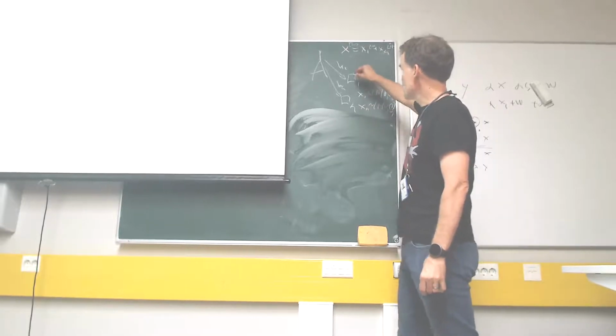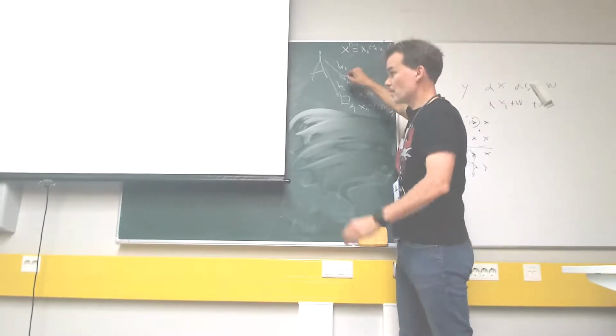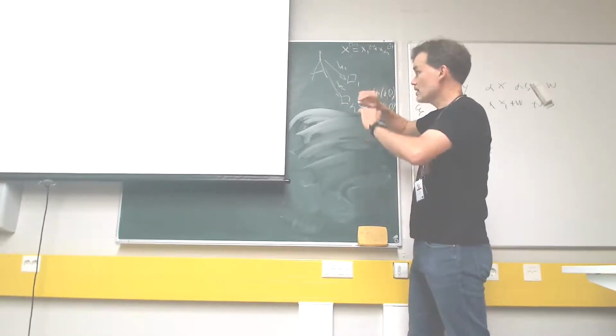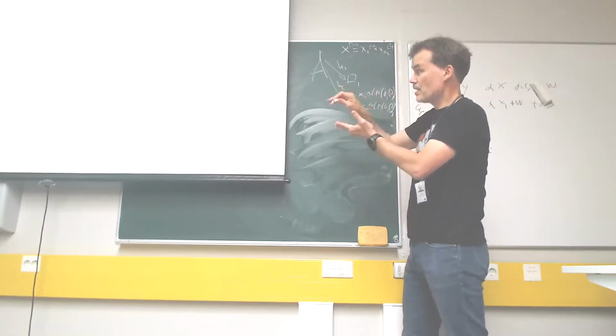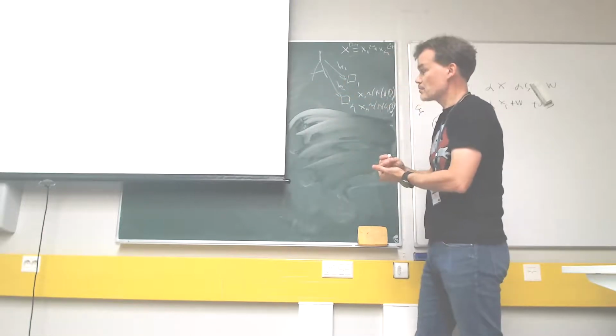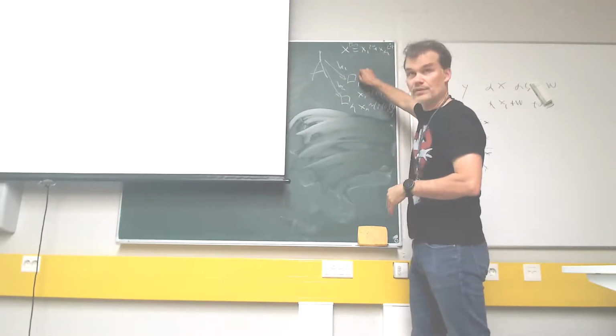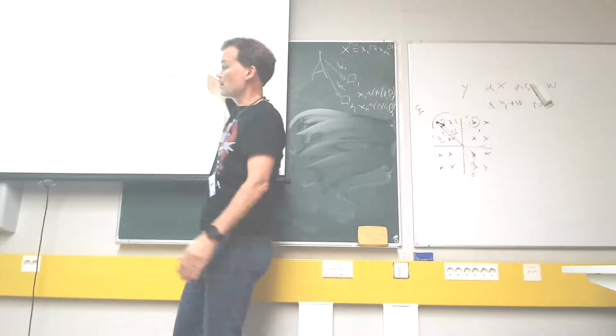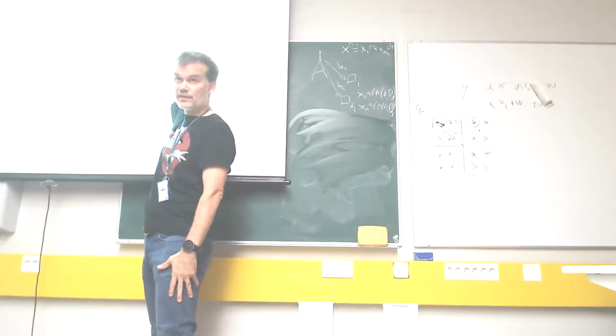And since user 1, because the channel gain is larger, its achievable rate is higher for given this x1, so it can also decode x1 and subtract, right? And it gets the same interference-free rate, right?